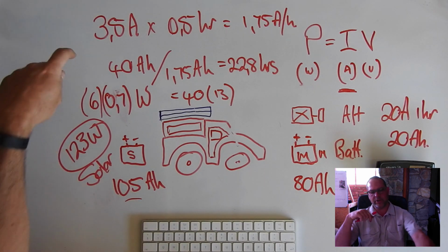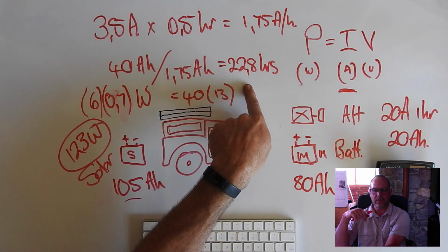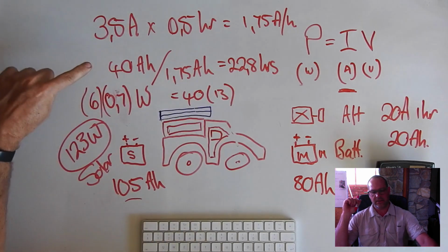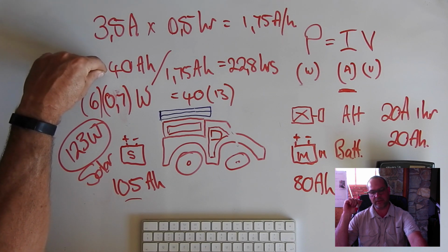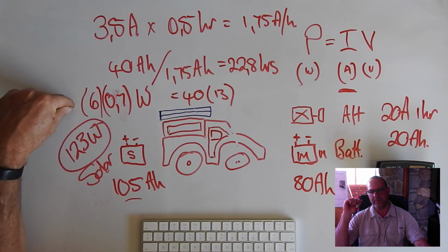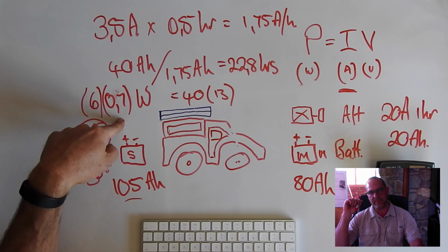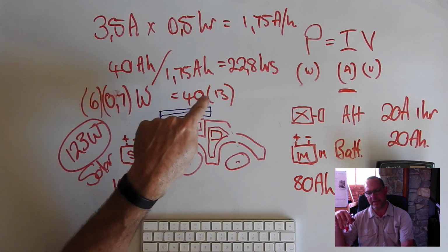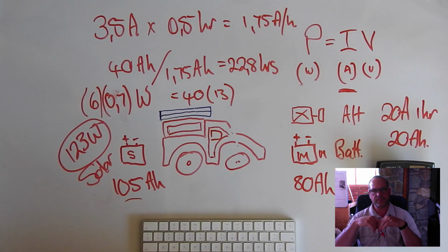So if I'm running a fridge, half an hour of every hour, it will last me almost 24-hour cycle, which is more or less what I'm looking at. I will drain 105 amp hour by 40 amps, so I'll bring the battery down to 60%. If I want to replenish it with a solar panel for 6 hours in the day at a 70% efficiency for a horizontal panel, I will replenish my 40 amps at 13 volts with a panel 123 watts. And that is basically how you would look at this.